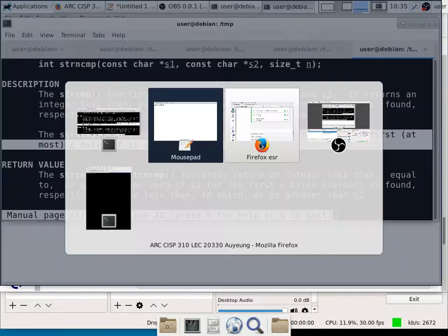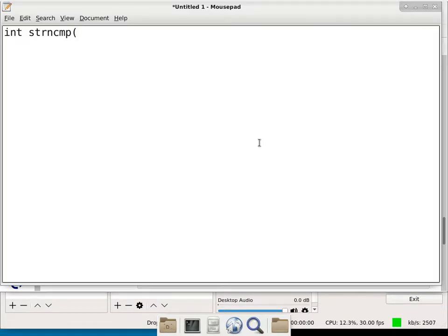Okay. So getting back here, we'll just write the subroutine in C first, and then we'll convert it into assembly. And I'm pretty sure this time we won't have enough registers because of n being a counter. Okay, so writing this in C is fairly easy because we don't have any limitations of registers.